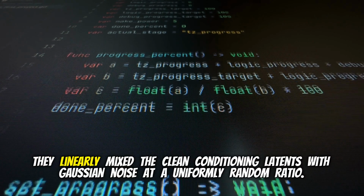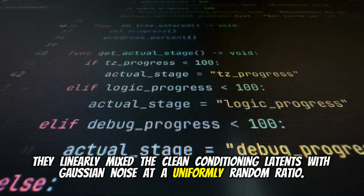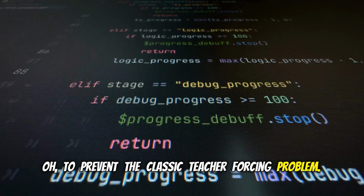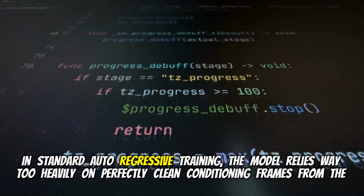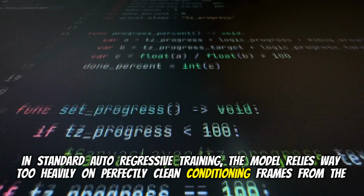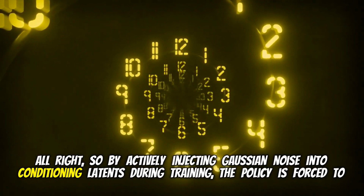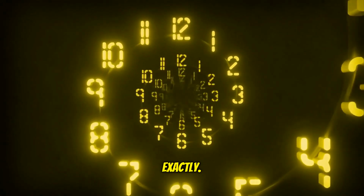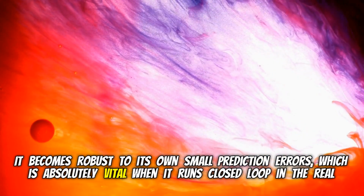They linearly mix the clean conditioning latents with Gaussian noise at a uniformly random ratio. Oh, to prevent the classic teacher forcing problem. Yep, where the model overfits to perfect data. In standard autoregressive training, the model relies way too heavily on perfectly clean conditioning frames from the dataset. Right, so by actively injecting Gaussian noise into conditioning latents during training, the policy is forced to learn how to recover. Exactly. It becomes robust to its own small prediction errors, which is absolutely vital when it runs closed loop in the real world.